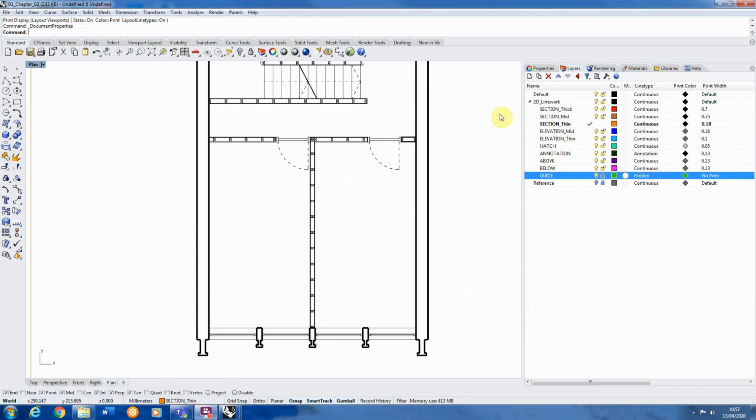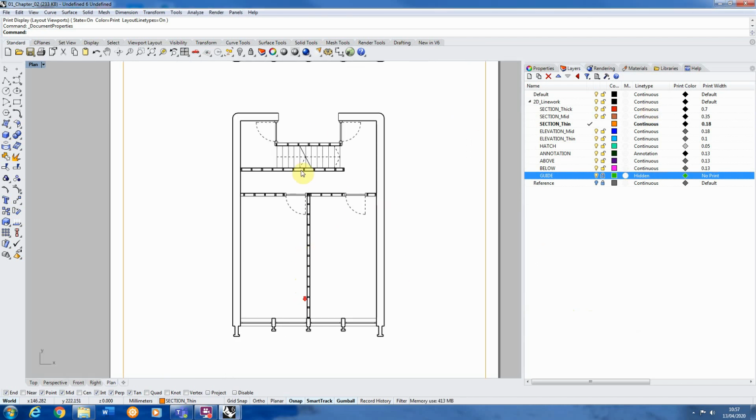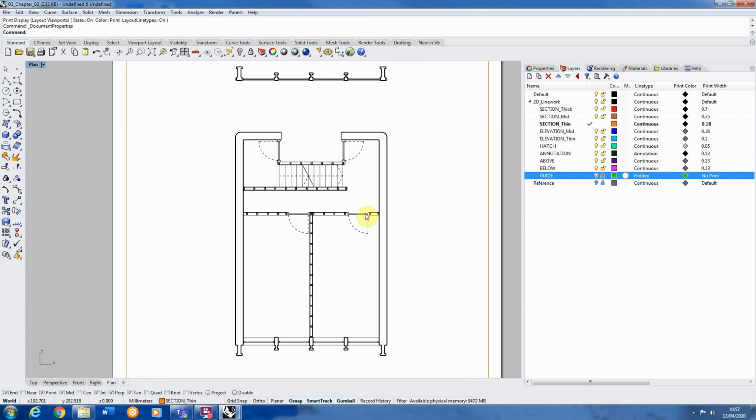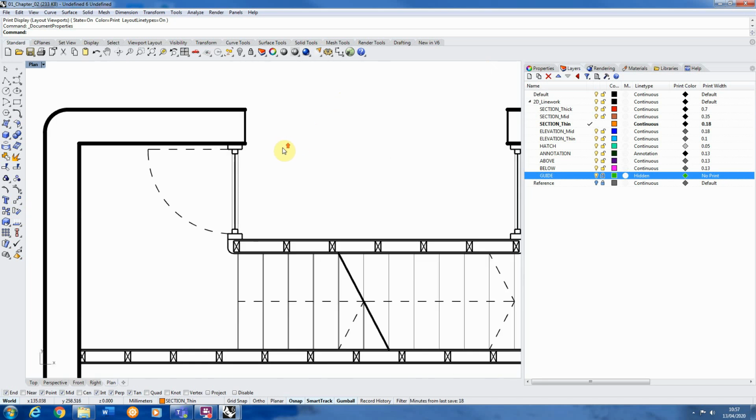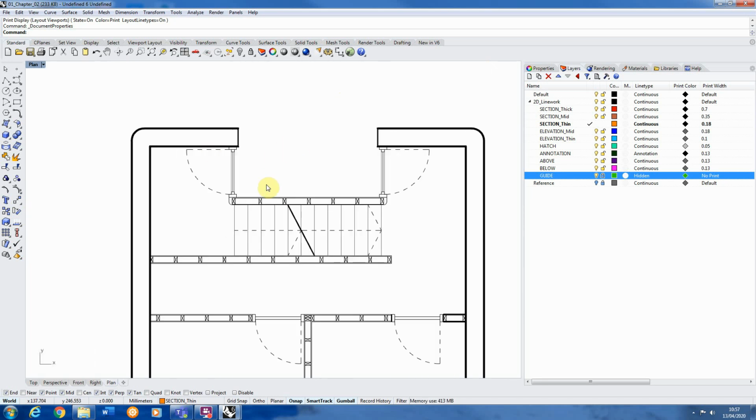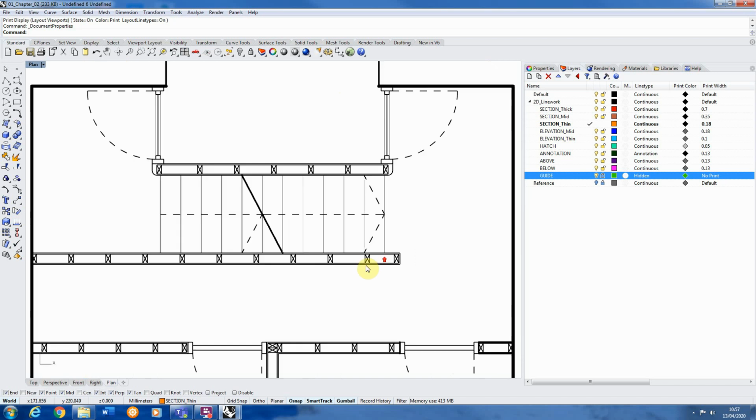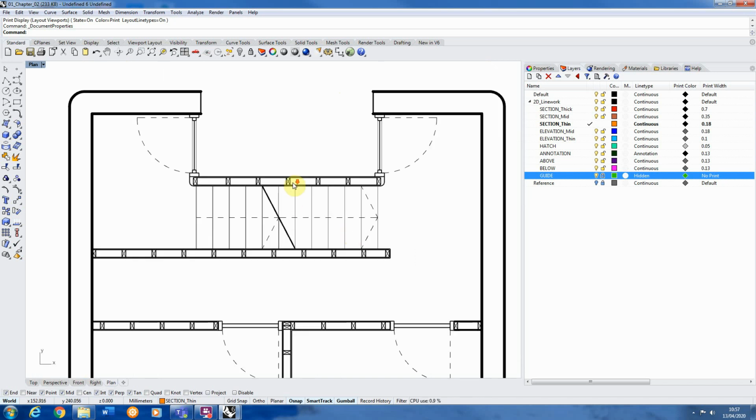So this is a good series of line weights to have for a drawing at around this scale, 1 to 50 or maybe 1 to 100. So you might want to copy out these different line weights into your drawings as well, as a good base point. But I'd always recommend doing test prints of these and checking how they're printing out. It might be that some lines are too thin and you can't quite see them, or some lines are too thick and they're overpowering others.